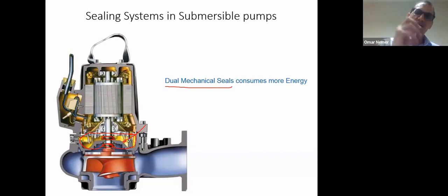We don't want the dirty water to go there to cool the seals, because if it did, these solids can destroy and break the sealing parts.